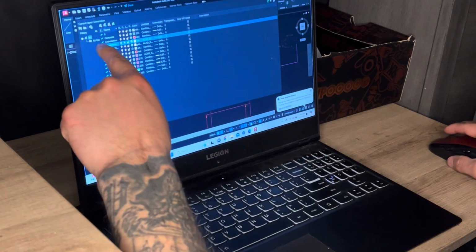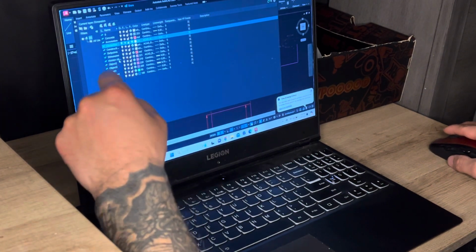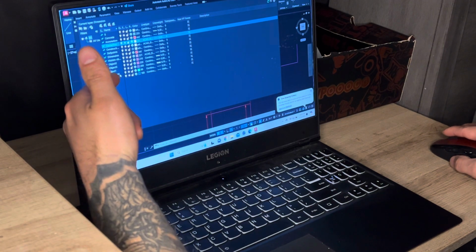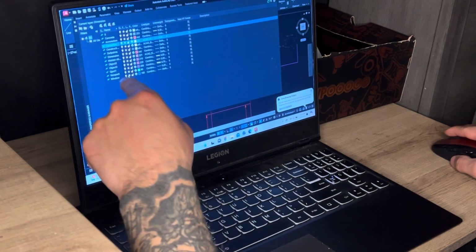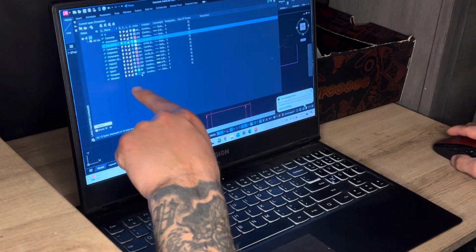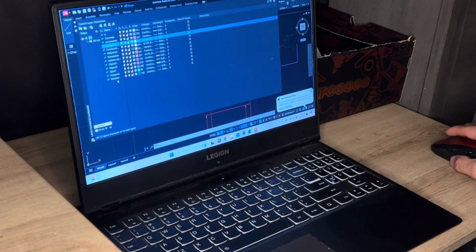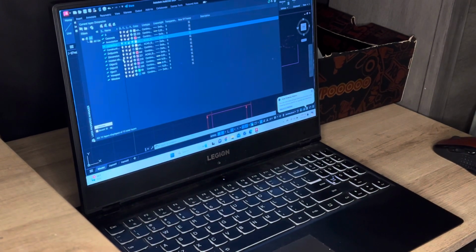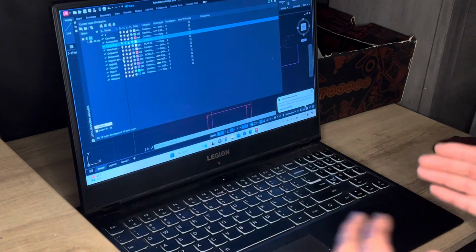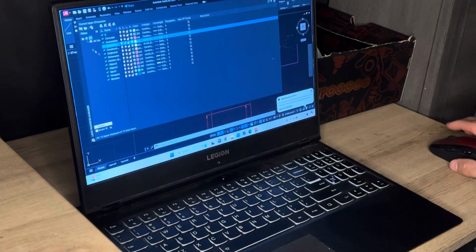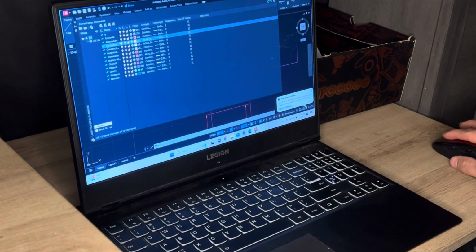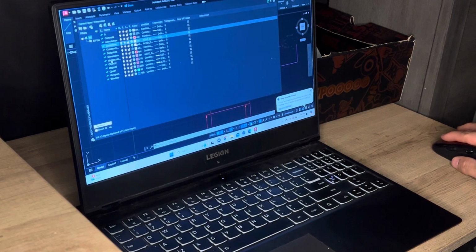So you can see I have a pretty good tool palette to start with now. I have 3 object layer lines. I have a viewport, which is going to be important for your paper space. I have a window, so I can draw windows. I could make a door one if I wanted to, but I probably would just use the window line for that. For me, drawing decks, it's not really that important to differentiate the doors other than to say where they're at in the drawing in relationship to whatever I'm building or altering, right? I have a dimension line layer, an annotation layer, concrete layer, and I have a hidden object layer.